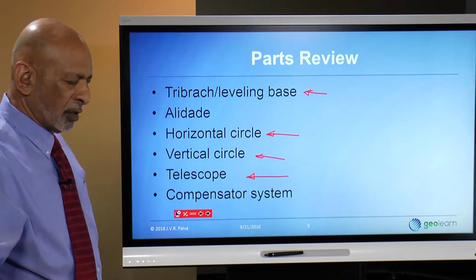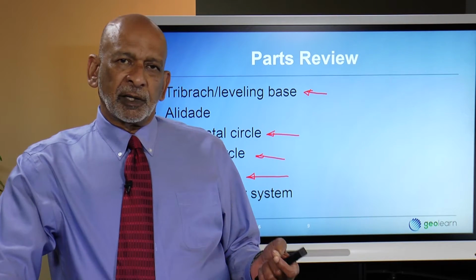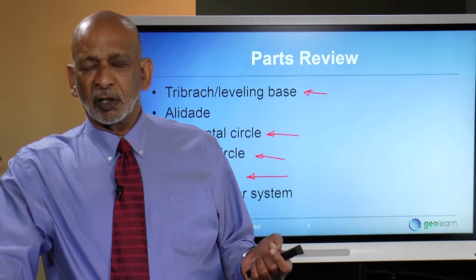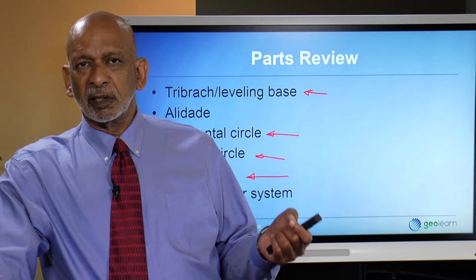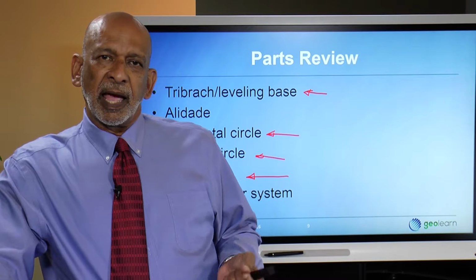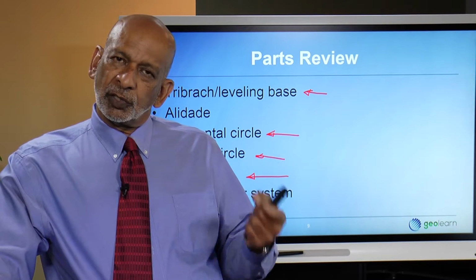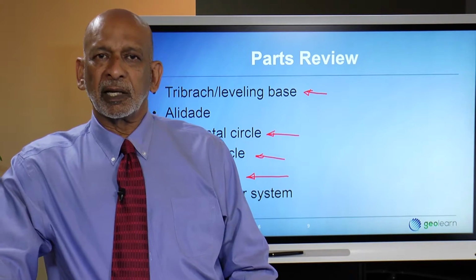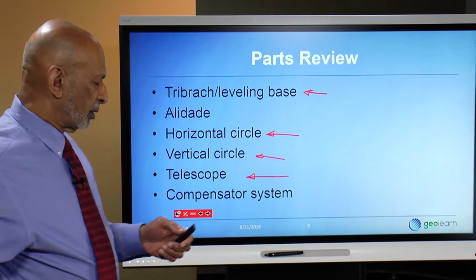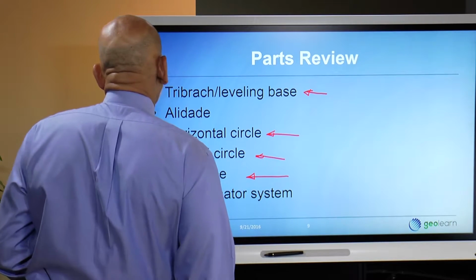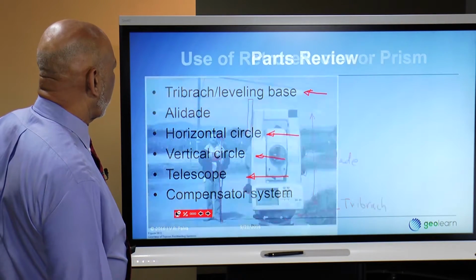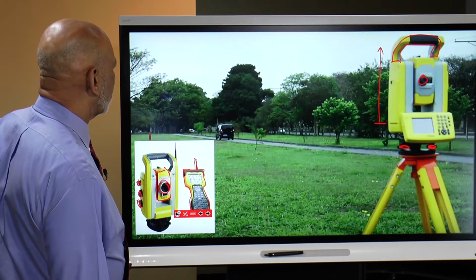Well, it turns out instruments are not perfect, people are not perfect. And nature doesn't help you out, because small fluctuations in the position of the instrument with respect to the vertical can change as the instrument warms up and cools down, especially if the sun is striking it directly, because you can have what's called differential heating and cooling. And so very early on, and this is one of the reasons why, let me go back to the transit picture again.